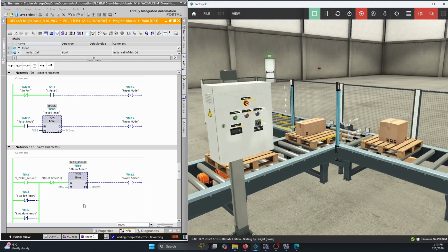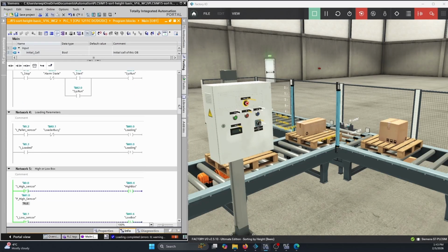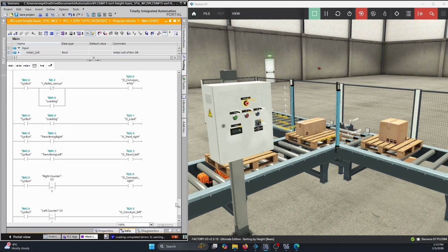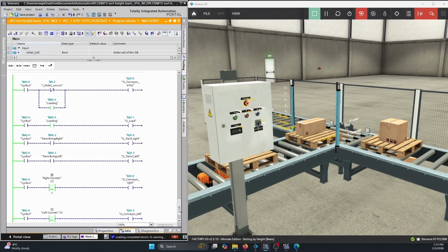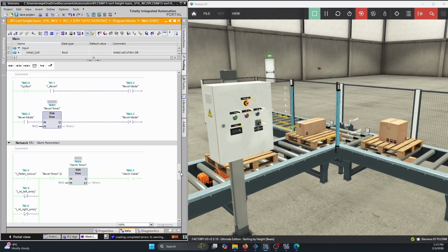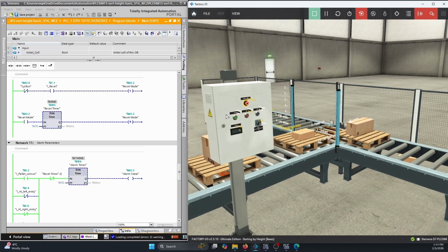Okay, we're going to stop this here. This is timing out. Now in an alarm state. Again, going up to system run. System run has been kicked out. Outputs are off at the moment. Nice. And if we go back to our reset mode and alarm state, then we can press the reset mode once. Okay, once it's done timing, it will take out alarm state. Now I'm able to turn on my system run, and everything's back and running.